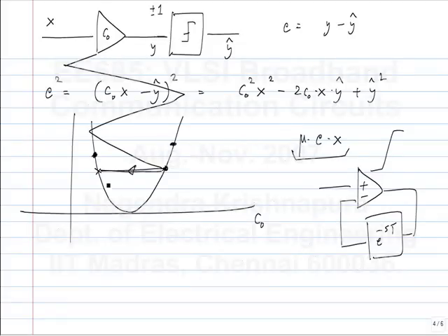At this point it's a discrete time system, so it doesn't influence it at all, because the value of t is kind of irrelevant for this. I have a discrete time signal and I make an FIR filter and I update the coefficients of the FIR filter. No, it doesn't influence it. What's the role of t here? I said that it gives you instability. How will t show up in the result of the circuit? The analysis I showed you was not dependent on the value of t. The frequency of oscillation is the only thing that is determined by t.